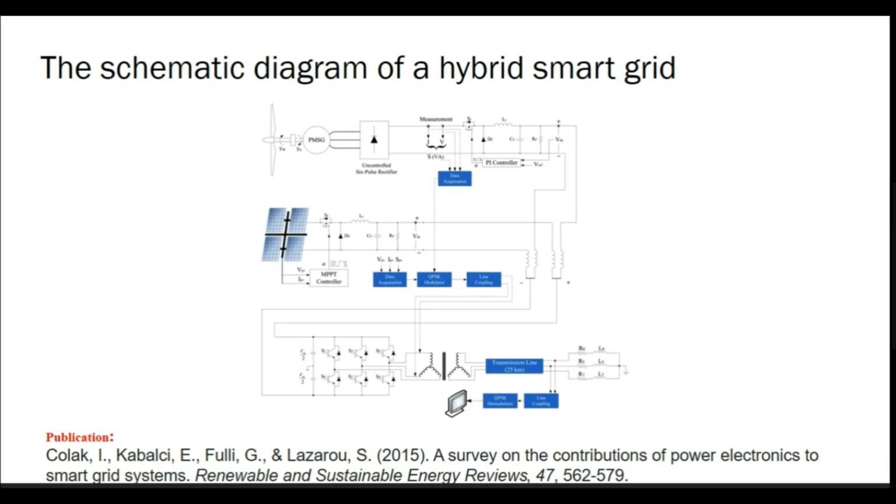So this is one example of connecting a wind system. When things are connected in parallel, obviously we know that the voltage levels have to be either in DC or in AC. It should be of the same form. But the output of PV is DC and the output of wind is AC, and hence we convert it into a common form, which is DC. So the solar voltage is boosted or bucked to a common DC voltage, whereas the output voltage of the wind turbine is rectified and maintained at the common voltage. That common voltage is taken to a 3-phase inverter, inverted, and then connected to an AC grid or the load system, which is AC in nature. So these are the common things.